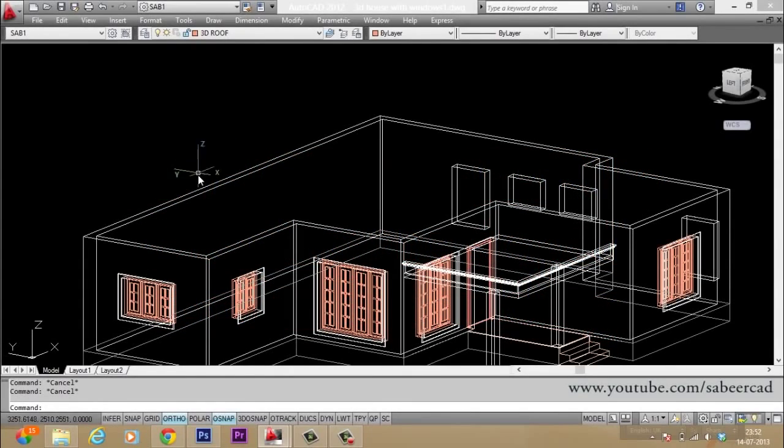In this video, I'll show you the procedure involved in creating a three-dimensional sloped roof for this house. Before we make the roof, we have to create a layer. I have already created a layer called 3D roof and made that the active layer. Now I'll trace the profile of the roof using a polyline. So I give the polyline command and pick all the necessary endpoints on top. And I'll connect with this endpoint and give a close to exit the command.